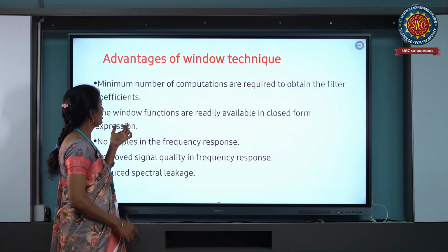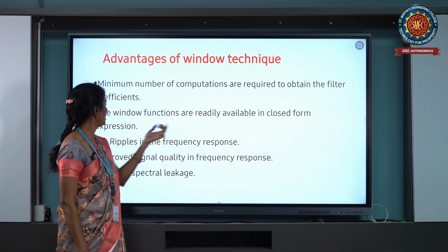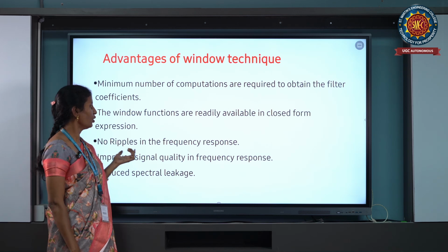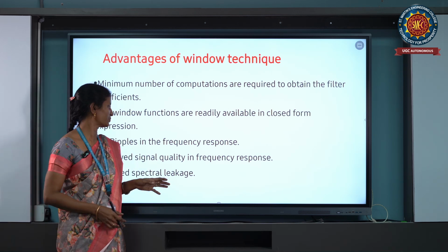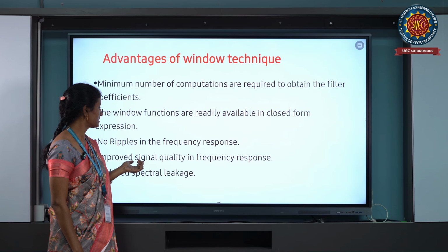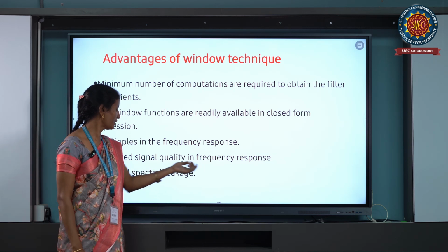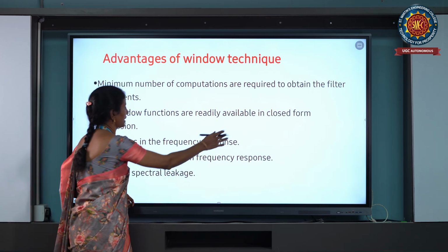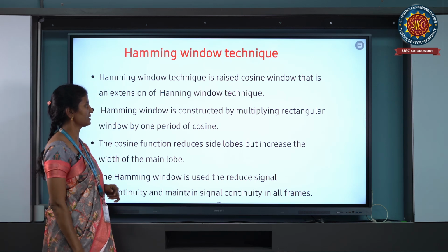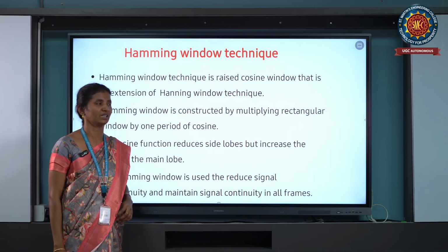The window functions are readily available in closed form expression. There are no ripples in the frequency response. It improves the signal quality from the frequency response and reduces spectral leakage. The spectral leakage is reduced using the window technique.